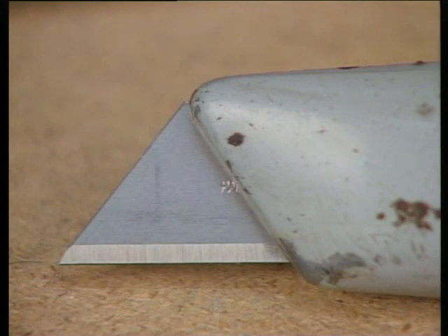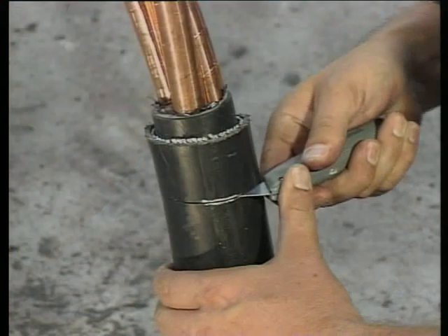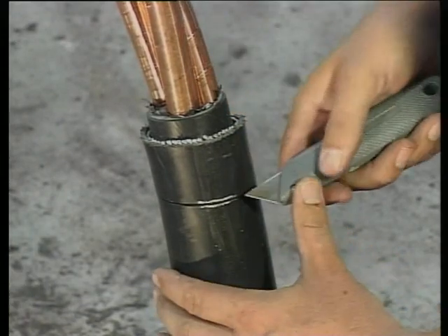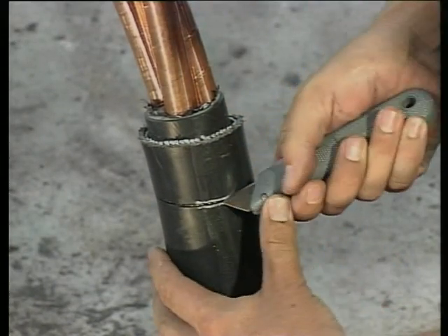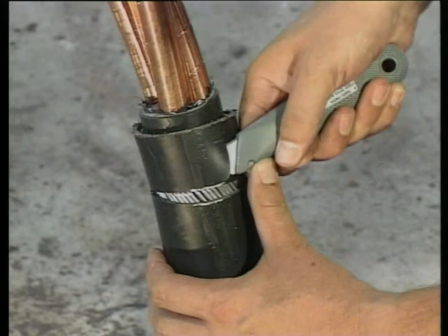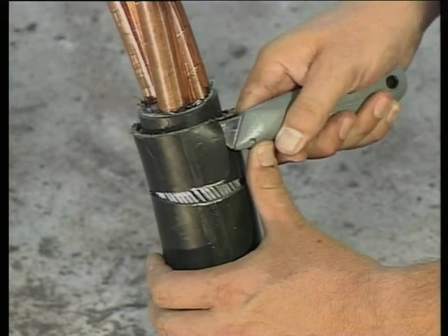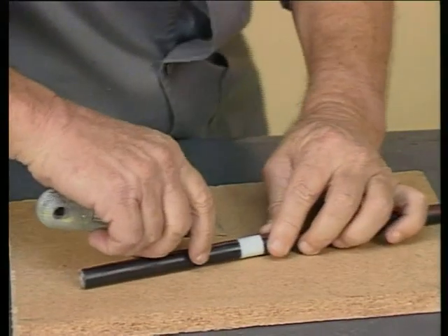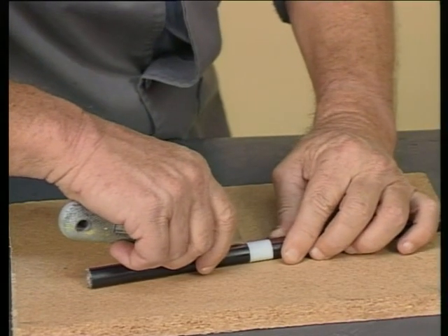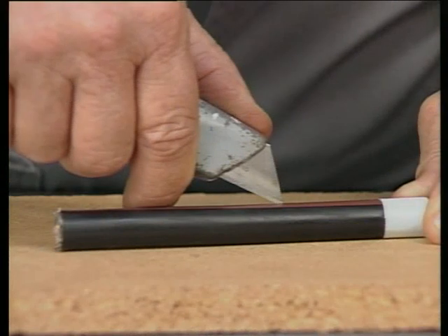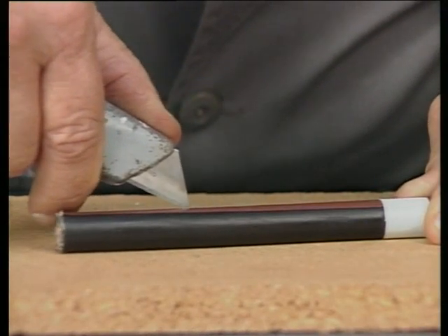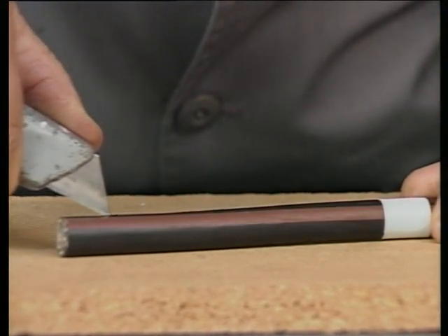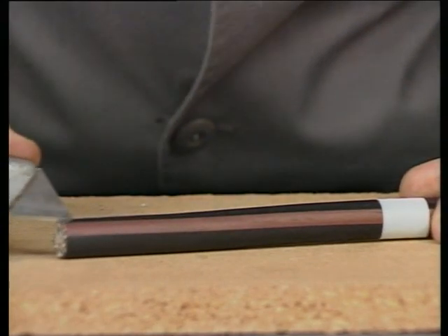up causing accidents. Sharp knives in the hands of experienced electricians can be used in virtually any situation which involves the removal of PVC or other soft materials. However, if you're not already experienced in the use of a sharp knife, then it is suggested that you perform your cuts as demonstrated, using a cutting board or rubber board whenever practically possible.